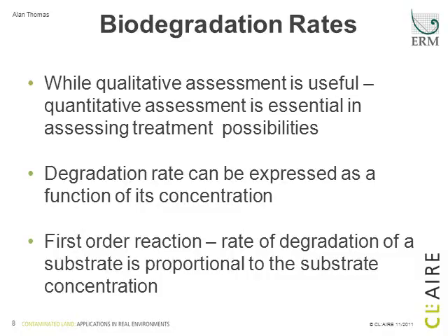As I mentioned, biodegradation rates are a critical part of in situ bioremediation design. Bioremediation is occurring at a set rate, and unless you have the residence time within a reactive zone or within the subsurface to allow that reaction to proceed completely, then you may not get full degradation or optimized degradation of your compounds of concern. So while we can do qualitative assessment of biodegradation rates, very often we also look at quantitative assessment in remediation design